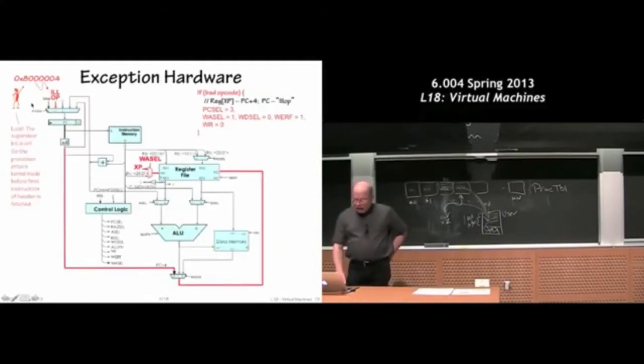Okay, so these illegal operations that we're going to use are just detecting an illegal opcode. This illegal operation does exactly what the hardware interrupt does. It just goes to a different PC. So the external interrupt, the IRQ request, and the illop work very much the same. They just go to a different place in the kernel.